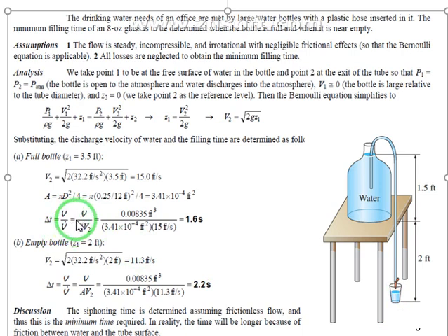So what is the flow here in this case, guys? We have velocity, we have area. We know that the flow is gonna equal area times velocity. So I can get it here. So time for the first case is gonna be 1.6 seconds. In the second case, the only difference here is this 3.5 becomes 2, because the water will be in this side here. It's almost empty. So we can get the time, which must be bigger than the first case. Right? This is very important. So that's how we can deal with such examples. So the answer is 2.2. I think it's very straightforward.